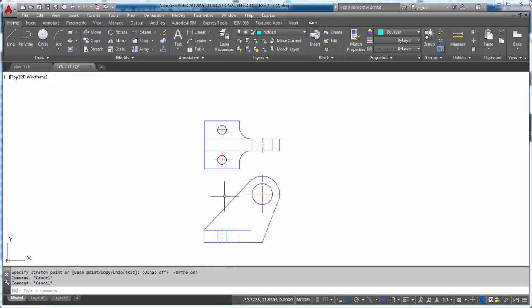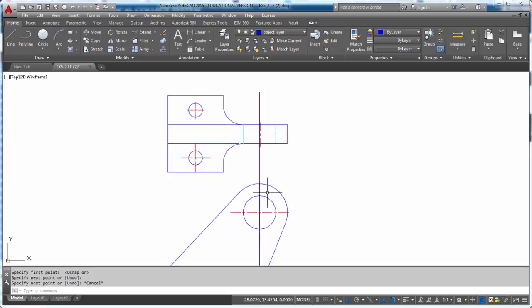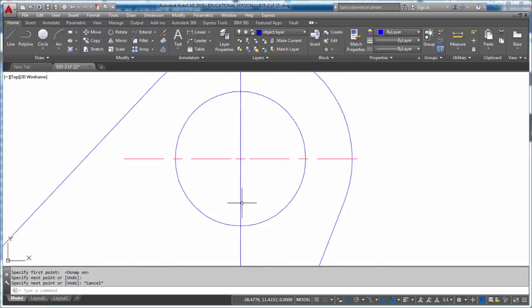And I think, let's see, this is a hidden line. Oh, hidden lines take precedence over, or are more important than, center lines. So here in this area, let me change to an object line. If you project up, you see it's right over the center.